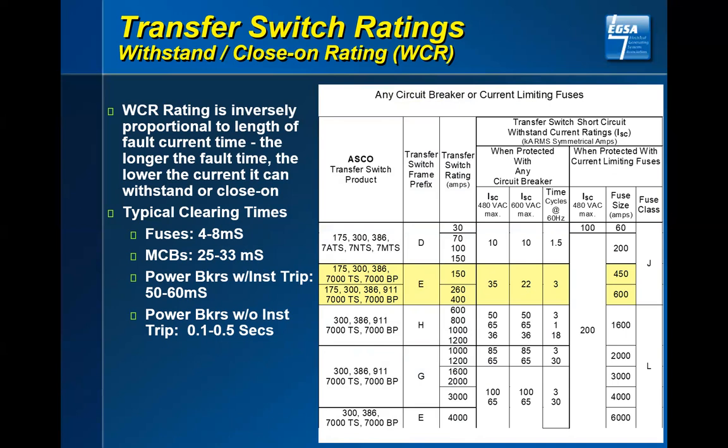The problem with that is you've done your due diligence, you have that breaker in place, and that breaker has a fault. You do not know what breaker they're going to send you from the electrical supply house to put in there. You may no longer be coordinated, and you may not be protected properly.